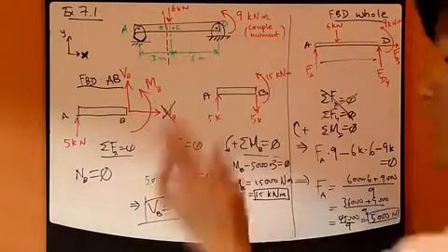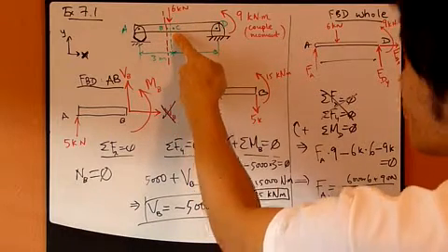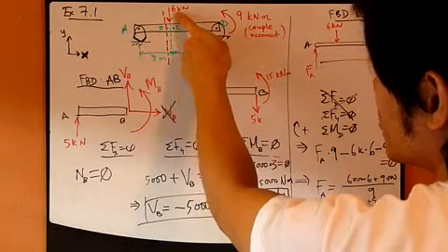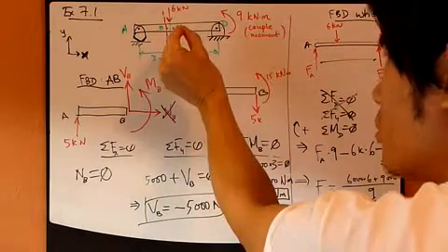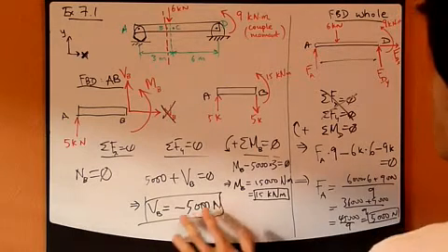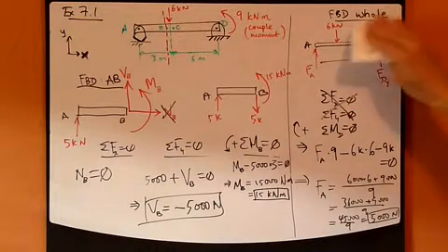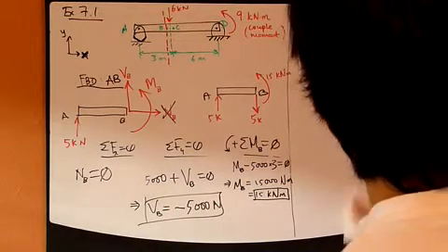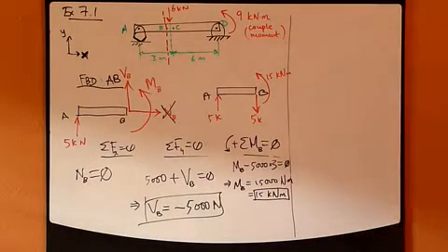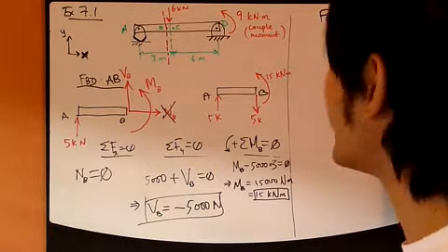Since B and C are really close to each other, really right next to each other, close to this line right here with the 6,000 Newton forces applied, you might expect that they might be quite close to what you calculated here at B. Well, let's look at it. Go through exactly the same calculation, except now you draw a free body diagram for a C section.